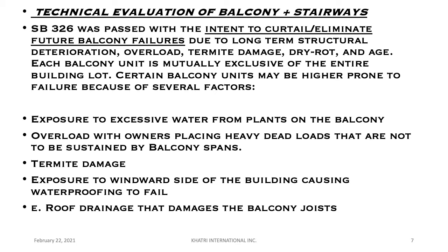You know, some areas of a building are more prone to termite damage for whatever reason. It's subject to water leakage. Maybe the roof gutters aren't working. There's all kinds of reasons that could be happening. And so that's why all the balconies need to be inspected. Exposure to wind forces. Some areas, like in Santa Monica, if the balcony's on the west facing elevation, which faces the ocean, they see a lot more wind, a lot more salt water than, say, the eastern exposure. So again, each balcony is mutually exclusive. And then, of course, the last bullet point, existing roof drainage can damage the balcony joists as well.